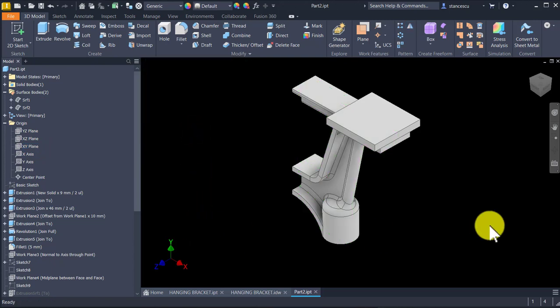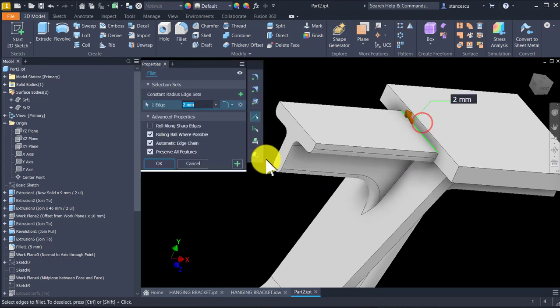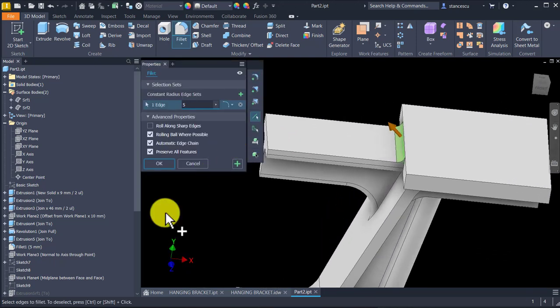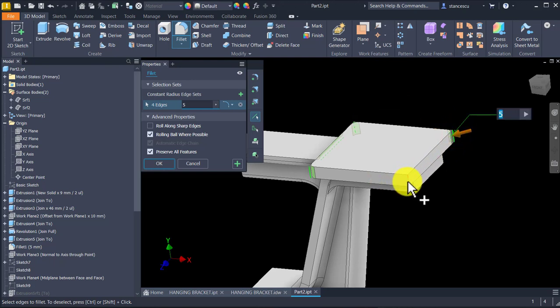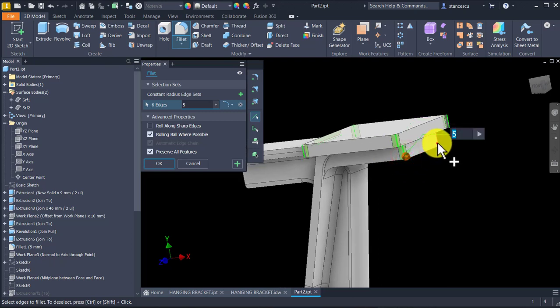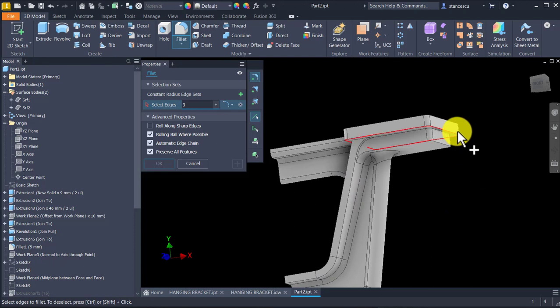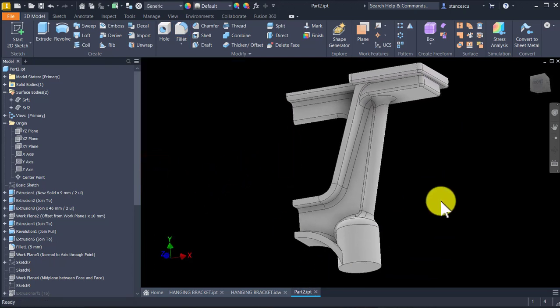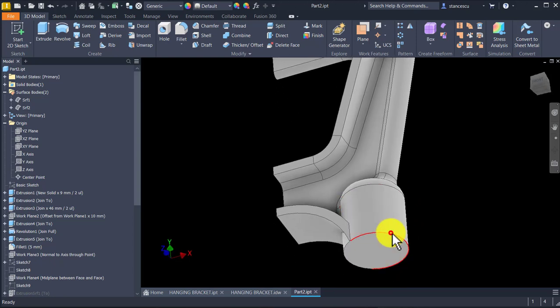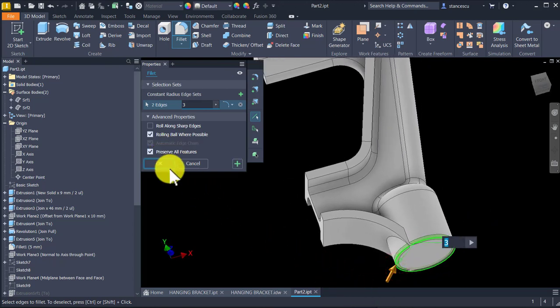Okay. And then we apply fillets for the entire half of the part. 5 is here. 5 is also to the corners. Them, plus 3 for this and this. Okay. Also here we apply 3 millimeters fillet. 3. Okay.